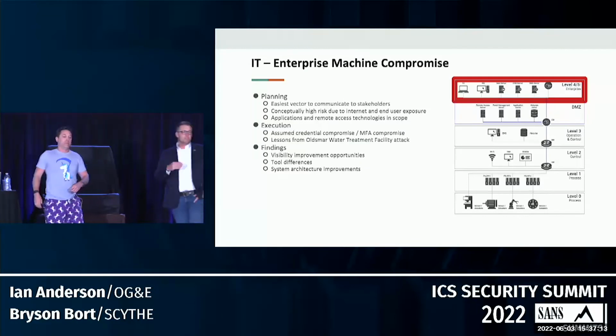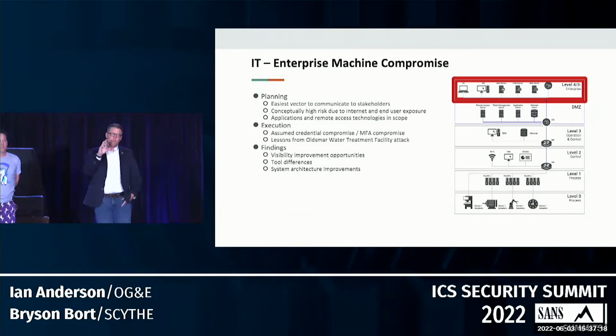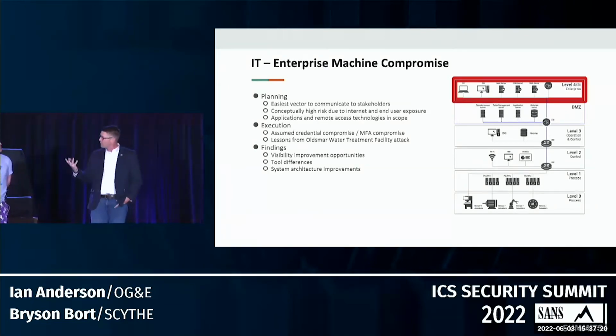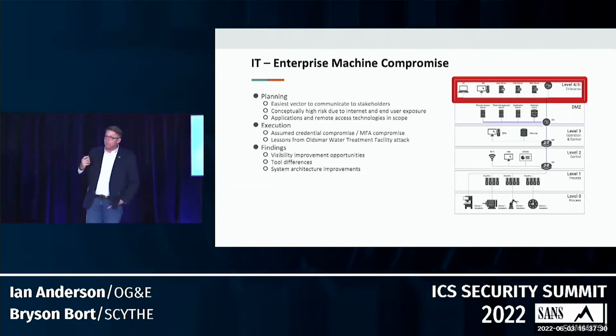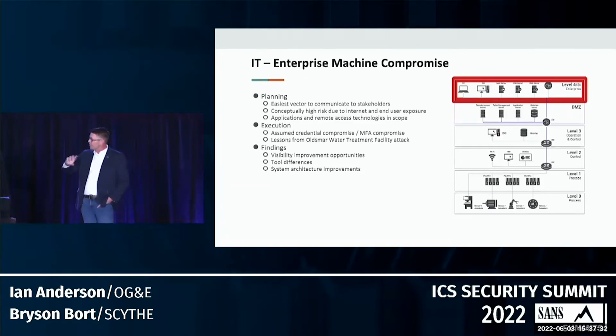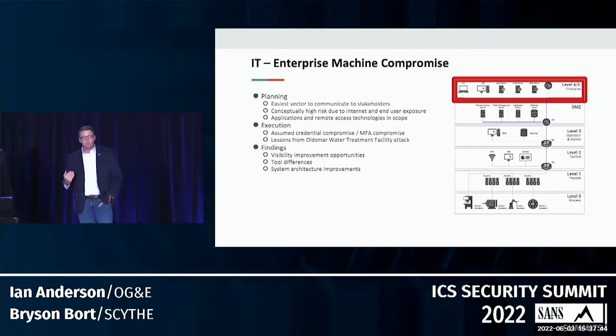Yeah, so let's start the journey into OT. If we accept some of the lessons from the ICS Kill Chain, we believe that OT attacks are going to emanate from IT. That is the most likely scenario. And we don't necessarily want to deal with odd ends or stunt hack stuff, like, well, technically you could do RF transmission into a keyboard or whatever. We want to ask, what is the likeliest approach for malware to get into our OT environment? For many organizations, it's going to be through the IT environment.